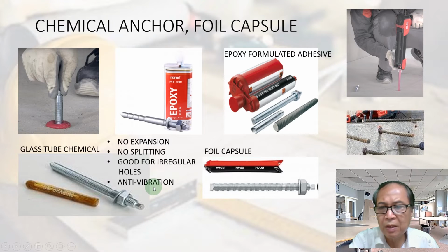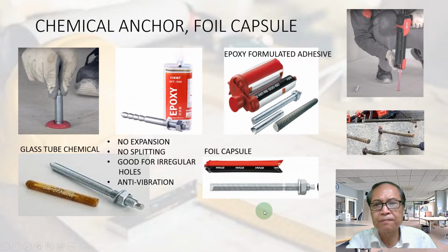Anti-vibration. This is a glass tip chemical anchor. You see, this is the adhesive, the chemical inside the glass tip. We insert this glass tip first into the hole. And this is a foil capsule. Of course, we insert the capsule first.